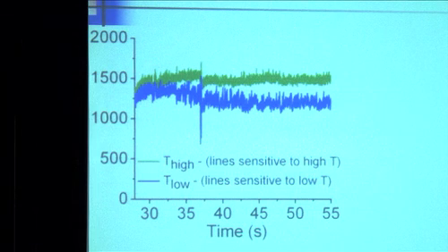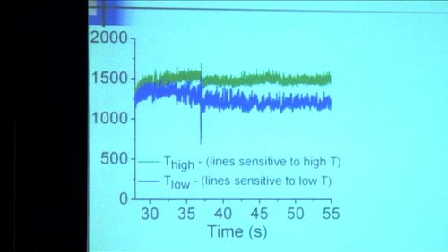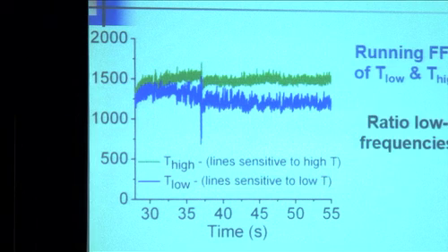And if everything is uniform, they're the same. They are right here. But he's picked out a sample of time from 30 to 55 seconds where they begin to drift apart. How can that be? What we decided was that the flow was beginning, the early stages of what's called unstart. It was beginning to become non-uniform. So it was nice and uniform, and all of a sudden it starts to unstart, and these 2 temperatures drift apart. And at first we were trying to understand the difference in temperatures to sort out the non-uniformities. And then we realized that there was something better to do.